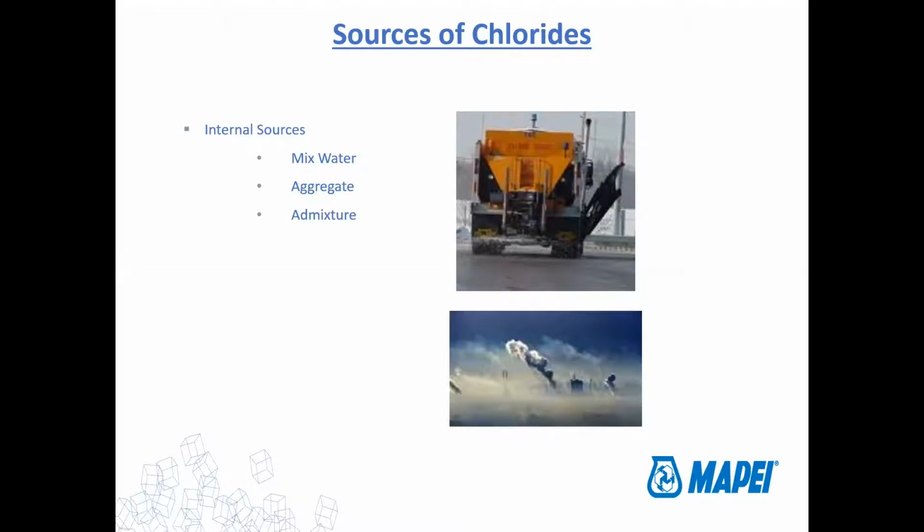What they didn't know at the time was that by adding all those chlorides to the concrete, they were creating a really tough situation down the road once all the corrosion started to initiate, which of course it did. So oftentimes when you go to a big city like Chicago or New York, you can tell the buildings that were built before the 1970s, 1975 or so, because 4 or 5 floors of the structure look really good. Then you've got 4 or 5 floors where you can tell they've done a lot of repair work, with a lot of cracking and spalling. Those are typically the floors that were built in the winter months, when they were adding the chlorides to the concrete unwittingly.